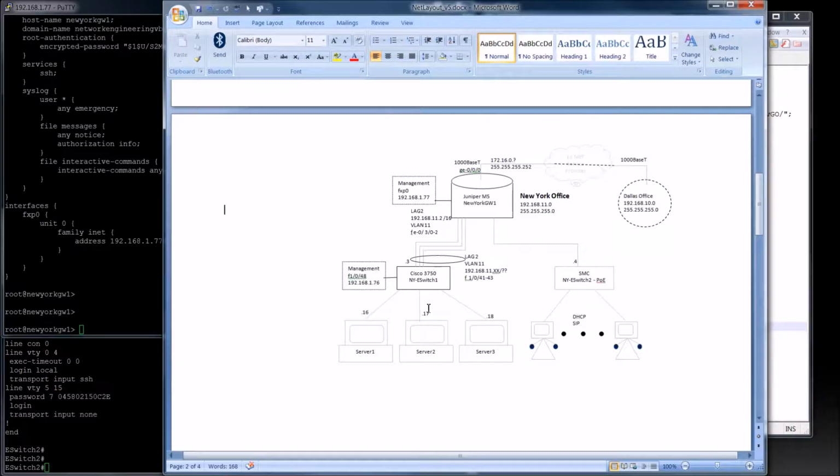These 3 links right here are the links plugging into the Xena compact test equipment. So the 3 ports will be the 3 links off the Xena I was showing you, these 3 right here on the access side, and then we'll plug in this 1000BASE-T port up here on the Juniper, and that'll be the 4th port on the Xena.